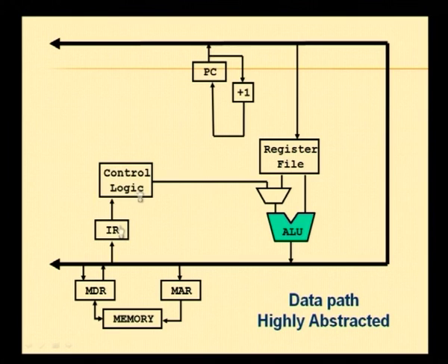So, that decode has to be done by this control logic. We will have some kind of a decoder or some circuit that is available which will identify the type of operation to be performed, right. So, that is the decode process. So, that is the second step.